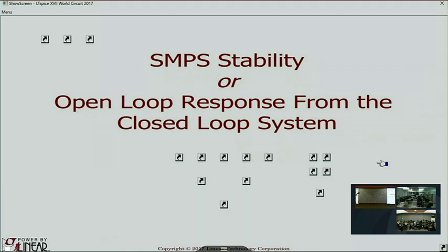Because this is 1 volt peak to peak, you have 12 volts in, you go 0 to 12 volts from 0 to 1 volt here. Okay, so that's your voltage gain. So this is now an E source, not a G source. And if that's a voltage, then that's a pole, and that's a pole. And the answer regarding stability of a feedback loop with 3 poles is that it oscillates, unless you have contrived it not to, either by inserting a zero to cancel a pole or by making one pole at such a low frequency you go through crossover before the other poles cause phase shift.